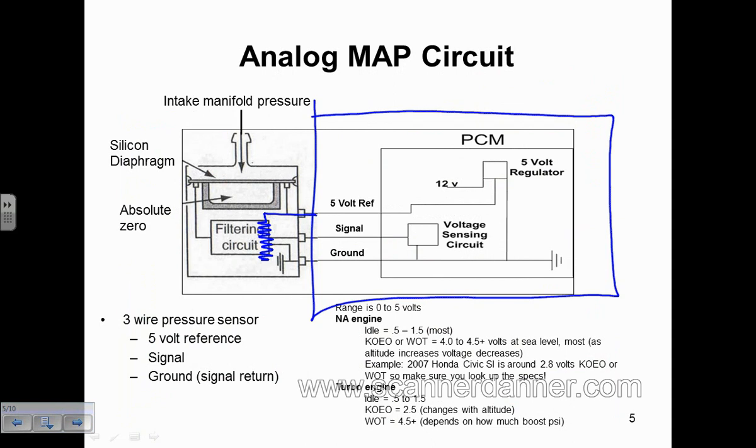and you've seen one already. When we did our 5-volt reference circuit, remember the description of the 5-volt reference and all the sensors that were shared. I pulled that wiring diagram up at the end, and I showed what the factory diagram looked like. Actually, it was a Mitchell diagram and the way they redraw them. The drawings of the pressure sensor, the MAP sensor, looked identical to the TPS on the wiring diagram. They drew it like this.